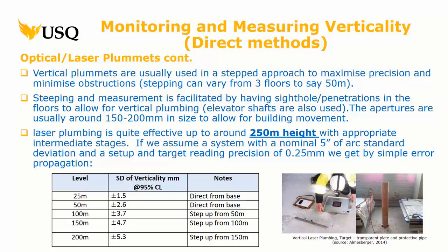You can see here, it's very hard for you to see, but maybe you can just see it, what he's looking at there is a plate sitting on top of the floor. The plate's gridded, right, it's transparent, and right in the middle, it is a bit difficult to see, is a red glow. That's the laser beam. So he positions this plate to where the laser beam is, right? And then most likely, depending on the circumstance, someone will set up on that and set out other points on that floor, right? But you can see you're going to need at least 2 points, and really to cover anything else you need a redundant 3rd point. That defines the plane of the floor and gives you some redundancy.